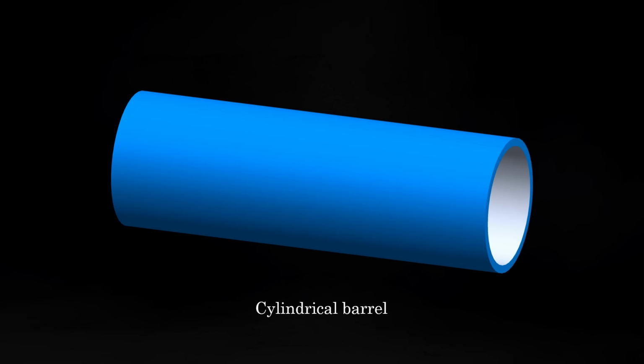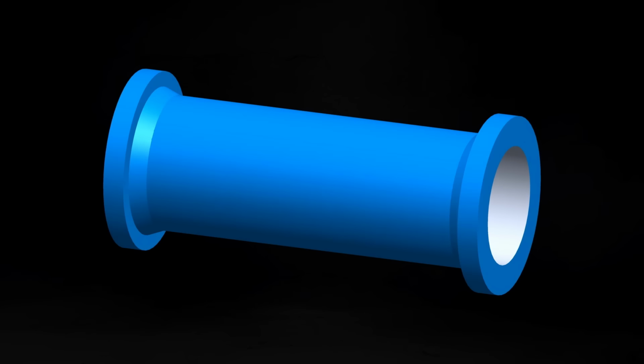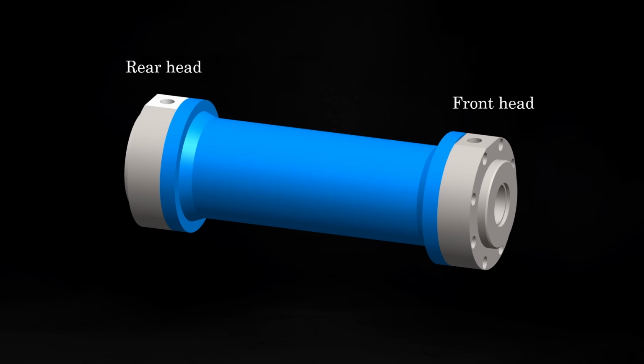Now, this video is going to be very detailed. So first, let me quickly make you familiar with every component of a hydraulic cylinder and how they work together. In a hydraulic cylinder, the first obvious component we have is a cylindrical barrel, a well-finished hollow steel tube, mostly made of mild steel, and it's bolted with the head.